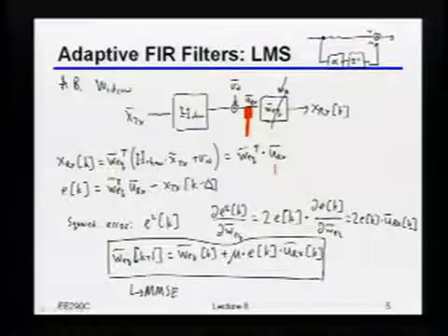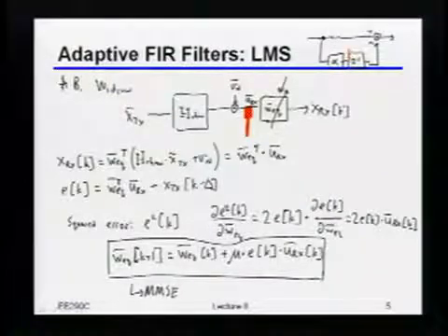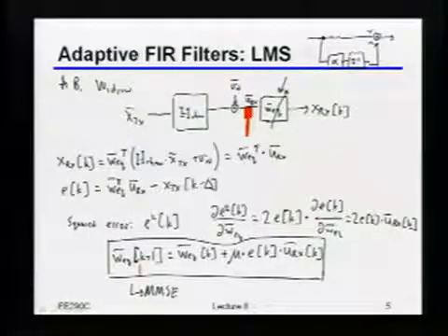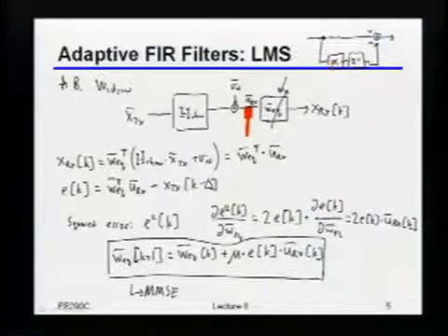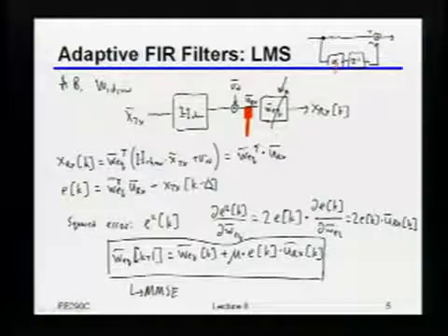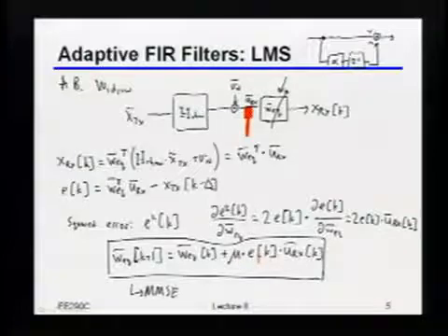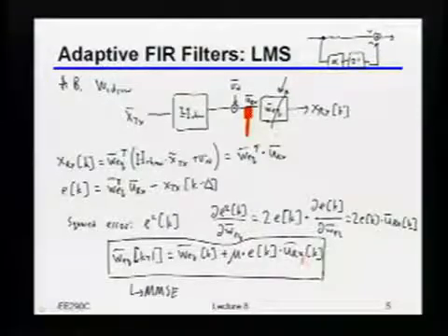Maybe just to say it another way, when I look at this one-tap example, the vector that I would be working with would only have 1 entry, because there's only 1 free coefficient that I'm tuning here. So I would update that coefficient by whatever that mu step size is times the current error times that vector, because I'm only able to tune that 1 coefficient. That's why I have to move this back by 1, because I'm doing the single post cursor.